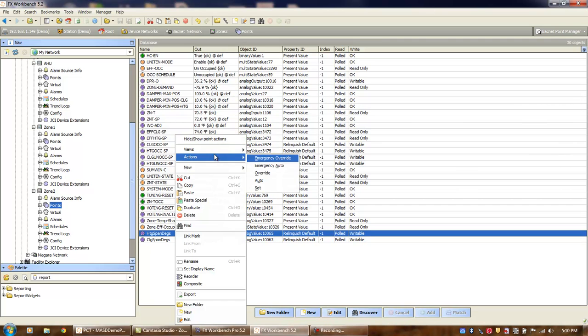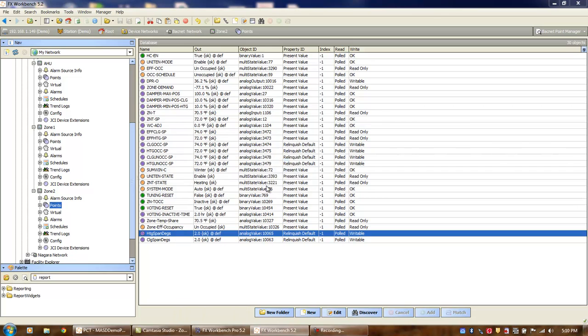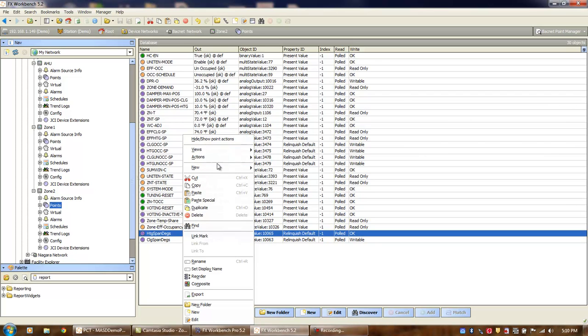If I want to, I can go ahead and adjust this and change the setting. And essentially what this is going to do is really change the authority for that zone in the heating. So now I've changed this from a 3 to a 5, and you can see up here that the zone demand dropped considerably at 5. So a heating span degrees of 5 will decrease the authority of the zone, and you can increase that up to 1.